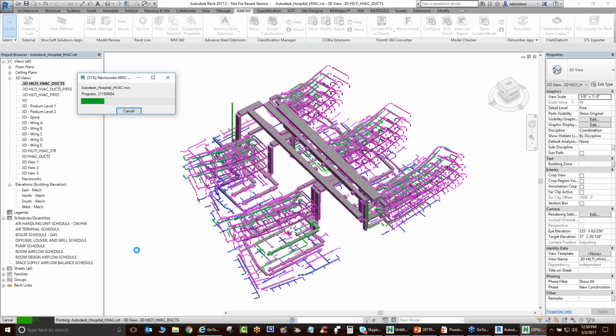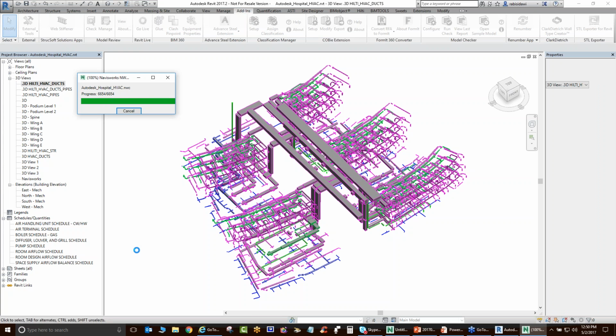So it's going through 6,000 components and writes the NWC file, which is a kind of lightweight file format for clash detection. So the process continues with every BIM model, whether it's fire protection, plumbing, electrical, cable trays, structural, floors, architectural walls, all the components that will make up the fire protection assembly.